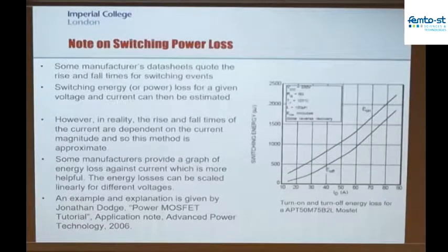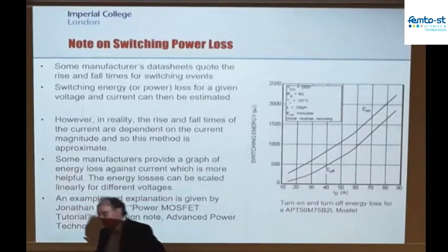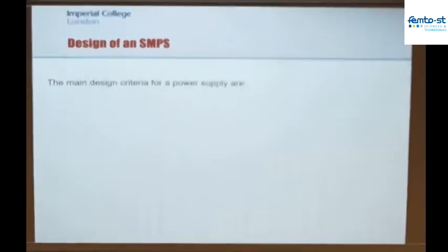So when you're designing a piece of power electronics, and this goes for anything from a large-scale converter for an electric train all the way down to designing something for an energy harvester, look at the data sheet. You need to know the loss values on the data sheet to be able to design this system properly.